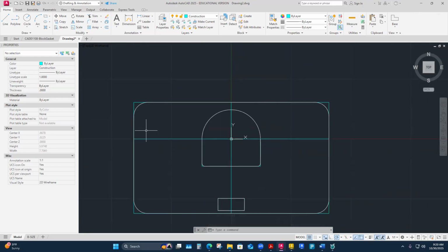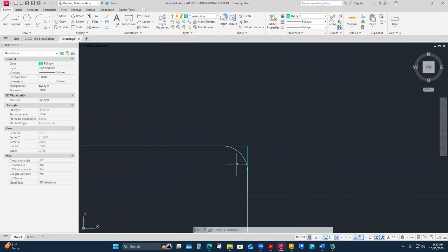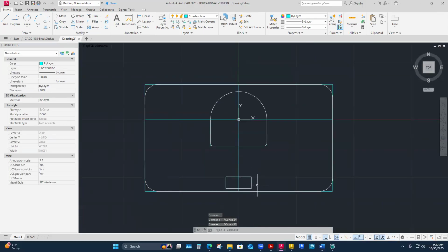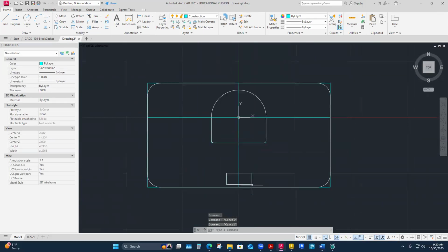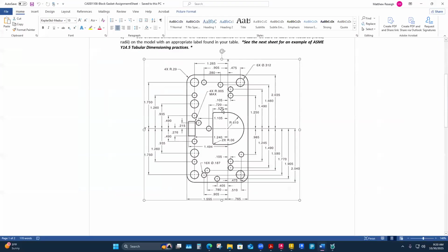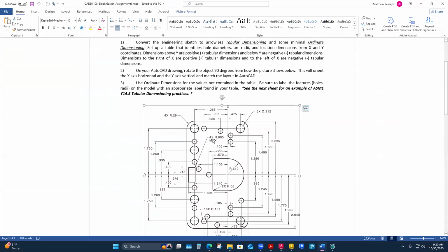That rectangle, the smallest fillet possible. They're pretty small. 5 thousandths a small fillet. Exactly right. Just barely, but required. Technically, it's got a weird term to it too. It says max. It's like I could make a bigger, or I could make a smaller one even if I wanted to. 4 times radius of 0.005 max. So it's actually critical that I'm not, yeah.